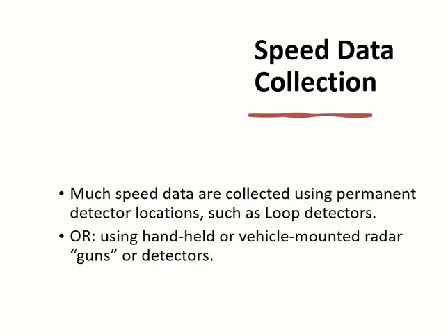Okay, now we move on to data collection, and then we will move to data analysis as well. So we are looking for a spot speed. You can do it using a permanent counter. The permanent counter, which is specialized for speed studies, is called a loop detector. They have installed it near many signals because signal yellow timing can change according to your speed. But it doesn't mean you can start coming at 200 kilometers per hour. The signal timing will change? No. It has a limit. It may change like a fraction of a second for you if you are too fast, but not more than that.